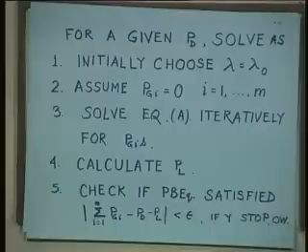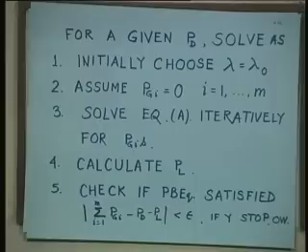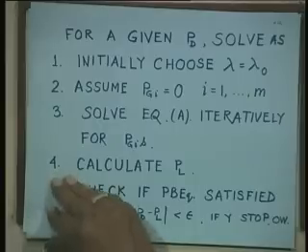So here the power balance equation is the thing where you can stop, see whether it is satisfied, because the whole thing is done to supply power to a given load. So the absolute value of sigma Pgi minus PD minus PL should be less than a certain epsilon, which is again fixed by you, depends on what accuracy you want, 10 to the minus 4, 0.001 or 1, whatever. If yes, stop. Otherwise continue.